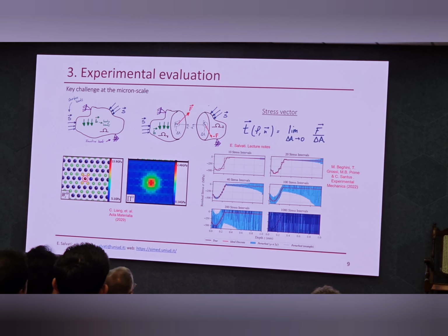If you have an SEM equipped with an EBSD detector in your lab, then you can also try to perform HR-EBSD. Okay, you explore and rotate it. You can extract some information about elastic strain. Okay, and essentially you, in principle, can reconstruct a full tensor if you know the elastic properties, so you go from strain to stress. That's very helpful. What is the drawback? What is the limitation of non-destructive techniques?